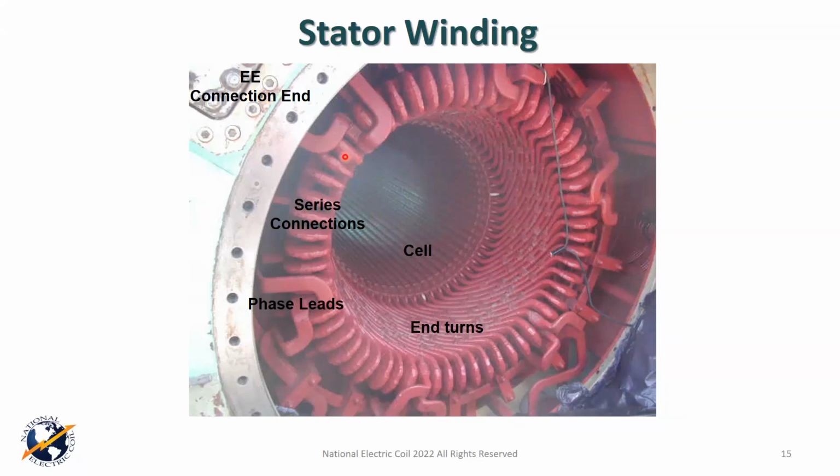Okay. We've got series connections here. You're just connecting a bottom coil with a top coil. There are some deviations here. There are ones that could be full coils where this is actually a knuckle. There are others that are made in bars, and we'll get into that shortly. They're strand connected, and there are others that today are very common to use clips on bars, but there are series connections and there are phase connections.